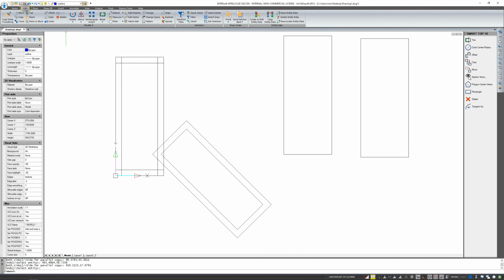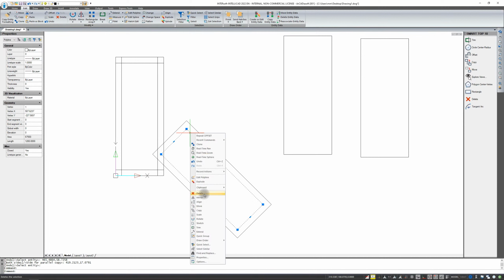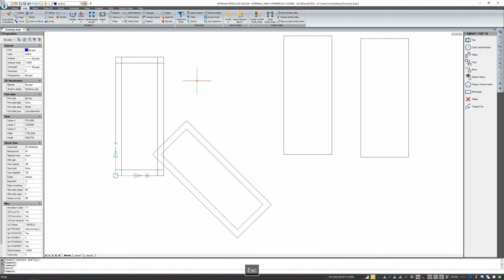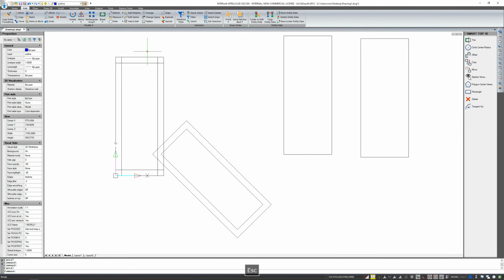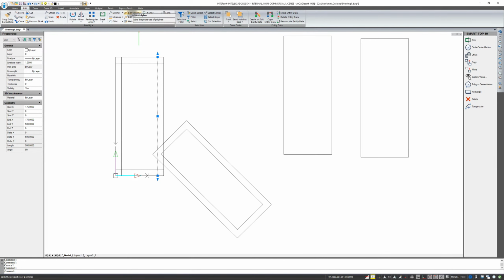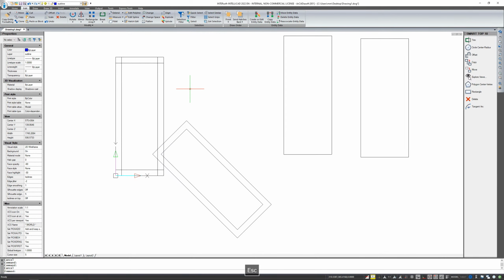Of course, you can always explode a polyline. Under the right button, you can choose the explode option, and then it will become an individual element. So this will be a line now, and if it had a part of an arc, it will be an arc. If you want to combine polylines into one line, use the option Edit Polyline on the Edit ribbon, and it will also be defined as a polyline, not separate segments of your polygon.